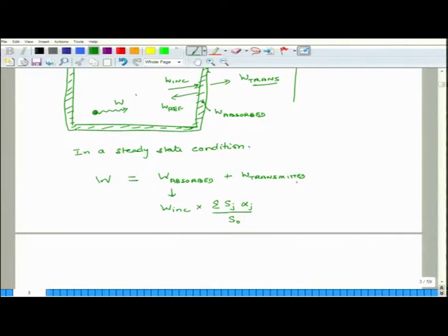And how much energy is getting transmitted? This is equal to, again, incident power. This is the amount of power which gets transmitted, so we have to choose each surface area, and each surface area is associated with a transmission coefficient, and I will say AT, and for the jth surface it is ATj, and this again is divided by the total surface area.